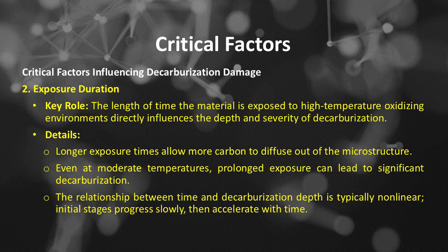Number 2 of the critical factors influencing decarburization damage is exposure duration. Key role: the length of time the material is exposed to high-temperature oxidizing environments directly influences the depth and severity of decarburization. Details: longer exposure times allow more carbon to diffuse out of the microstructure, even at moderate temperatures. Prolonged exposure can lead to significant decarburization. The relationship between time and decarburization depth is typically nonlinear. Initial stages progress slowly, then accelerate with time.